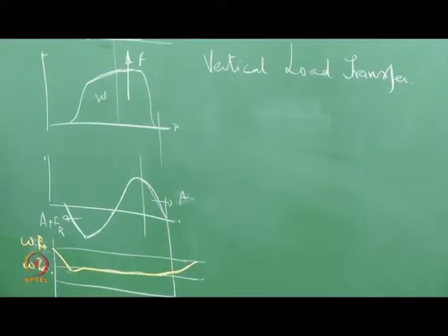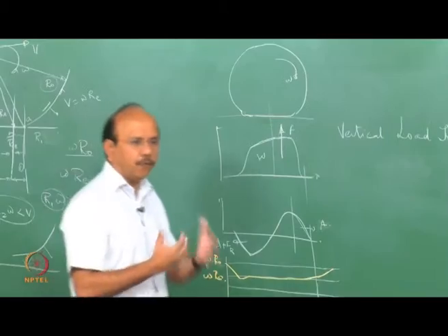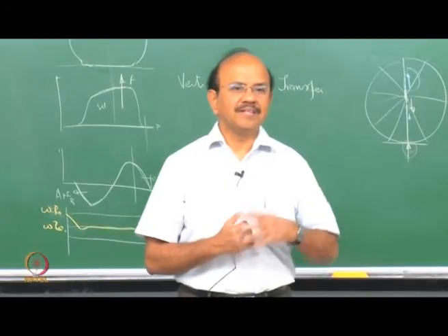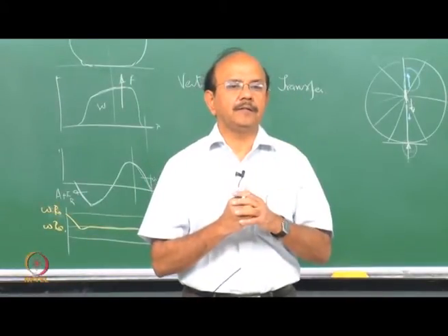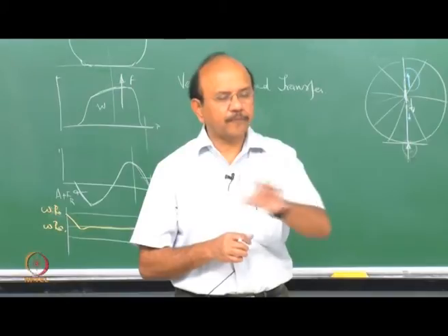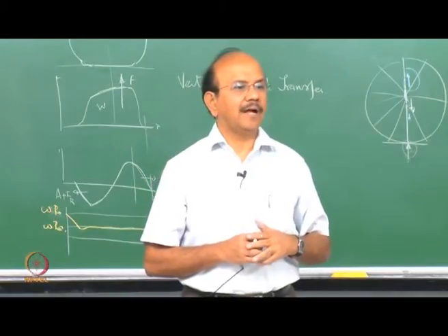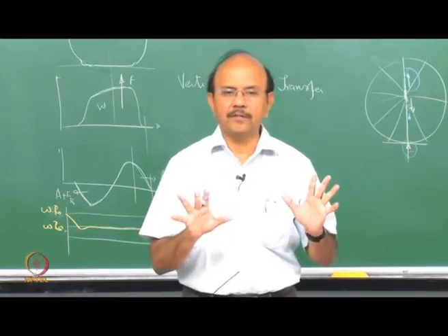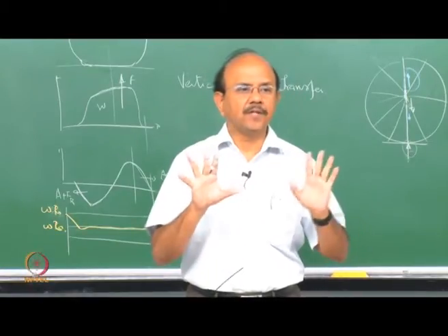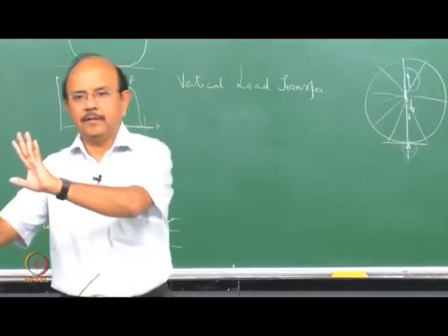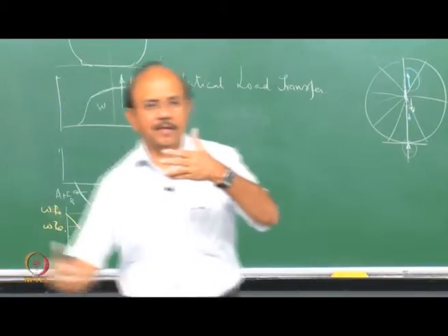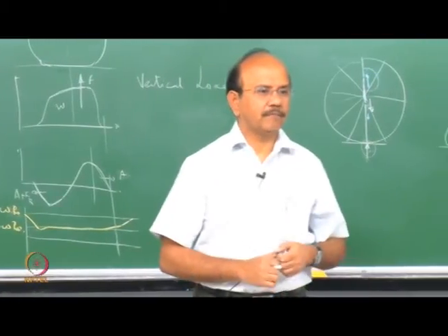So the lateral force developed depends upon the difference between the velocity of the wheel and the ground velocity. What is meant by ground velocity? We said that we can treat the motion of the wheel as if the wheel is stationary and the ground moves in the opposite direction.